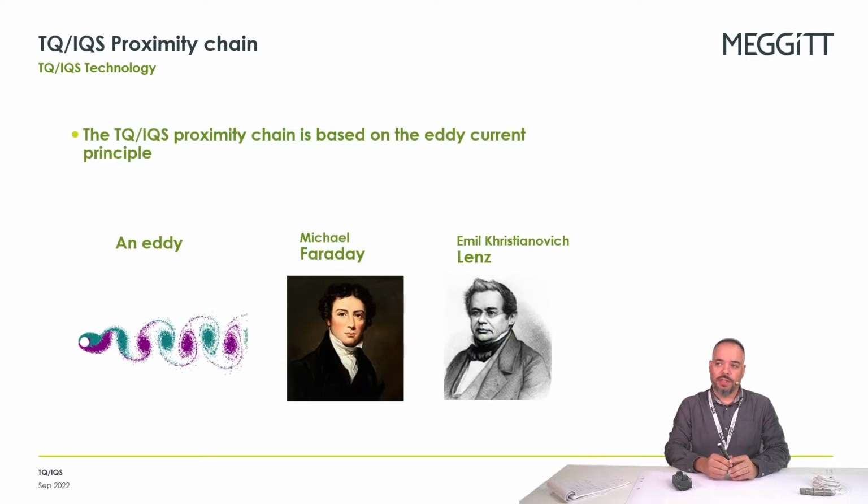By the way, and since I've been asked a few times, eddy is not the name of a scientist or a physicist. Eddy is the swirling of a fluid and the reversed current that is created when the fluid is in a turbulent flow regime, and this fluid dynamic phenomena is similar to the currents that are induced by a magnetic field, hence the name eddy sensors. If we want to name scientists that were fundamental to eddy probes, we must name Faraday and Lenz that define the equations we use today to design this type of probes.